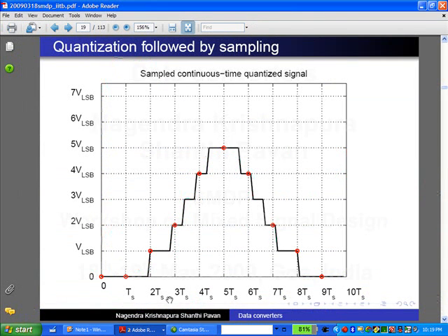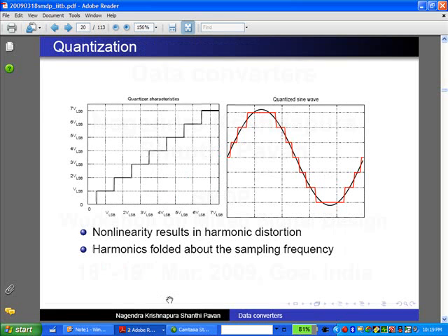So this is what I described so far. I first do quantization, which means that I am passing it through the nonlinearity on the left side, a step-like nonlinearity. Okay. So if I have this black sine wave, I will get this red step-like wave. We don't really care at this point what it is, except that because the sine wave is periodic, this is also periodic. So what will happen?